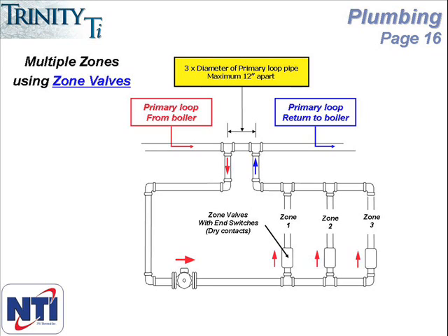This example shows the use of zone valves, so there's a single secondary circulator that will come on with every heating call. Depending on the size of the pump, this may be powered by the blue wire from the boiler itself, or may need a relay between the primary and the secondary pumps. Remember that the boiler itself provides 3 amps.